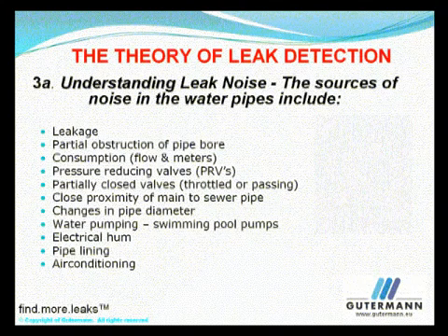As water travels through a reducer, noise is generated. Big reductions and high flow create more noise. The same effect is often found on S-bends. Low-frequency mechanical noises generated by pump stations, swimming pool pumps, and air conditioning can be heard. If the pipe is lined, this will usually dampen the sound of a leak, and the sound generated may be louder at the point the water escapes from the lining than the position where the water is actually leaking from the pipe.